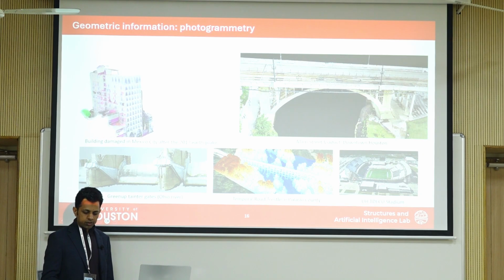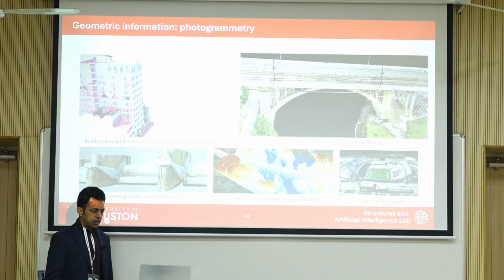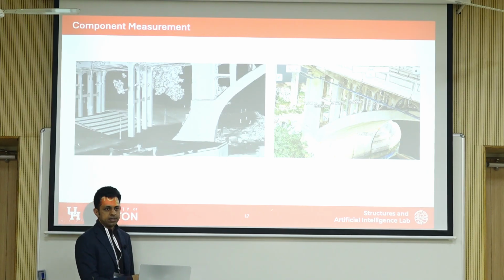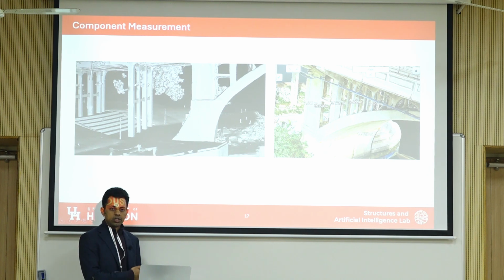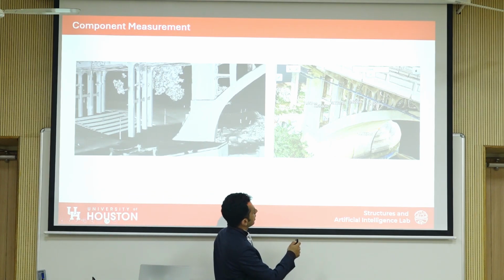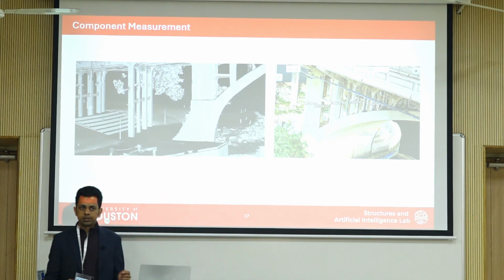That's more views of that 3D reconstruction of that building. Now, of course, once you do this, you get a 3D mesh, and then you can use that to make all sorts of measurements. Once you have this, it's much easier to do this than to go out and make these measurements. If I had to measure the width of the bridge from here, this is sort of inaccessible because there's a river here. I can measure it from the other side, but if I had to measure some defects there, that wouldn't be possible. But once you have this representation, then you can make those measurements.